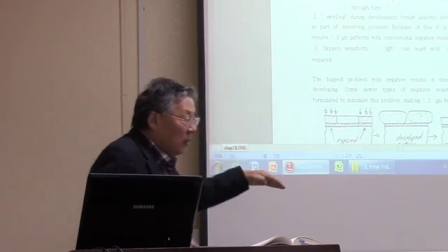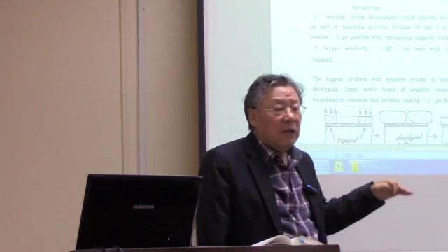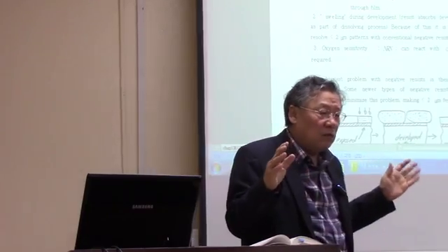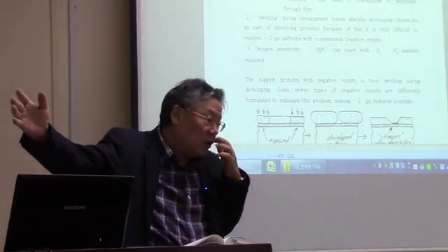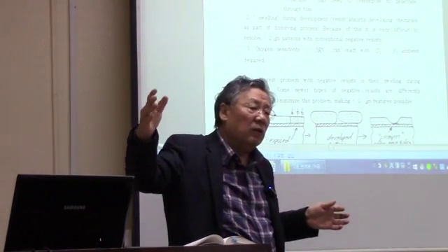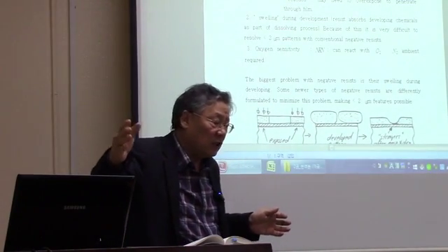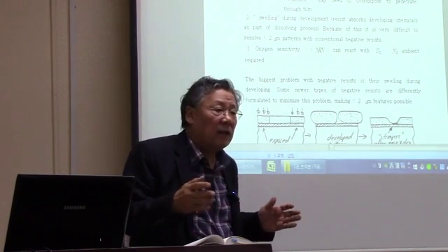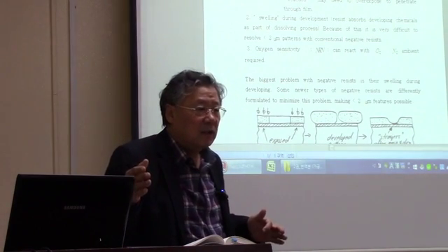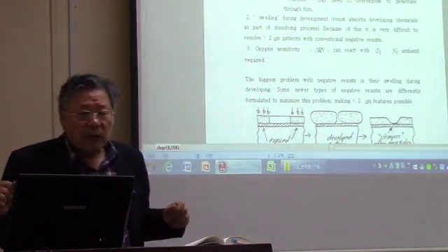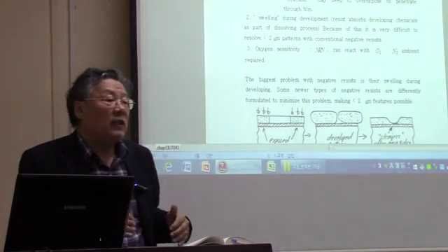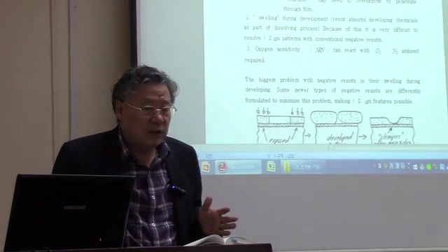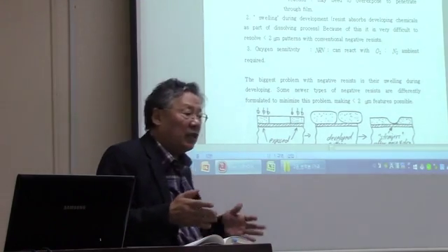So, before this, we just talked about the dry etching technique. And in dry etching, the industry people tend to move to the expensive machines like sputtering and ion milling and all those physical dry etchers, just because the resolution becomes tougher and tougher as you move to modern devices. So sacrificing the selectivity, people tend to use the high resolution dry etchers, sputtering or ion milling, things like that.